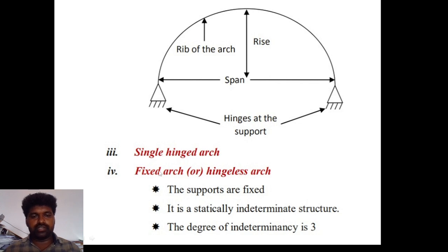Single arch, hinged arches, and fixed arches are hingeless arches. Supports are fixed. It is a statically indeterminate structure. The degree of indeterminacy is 3.